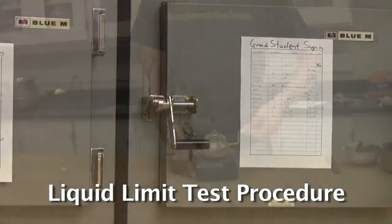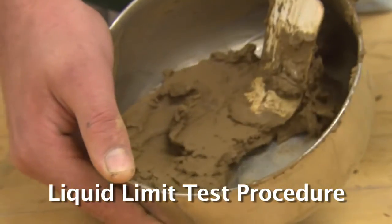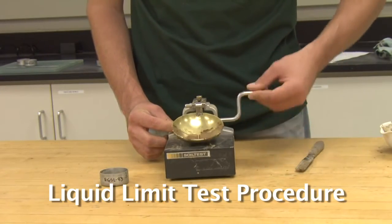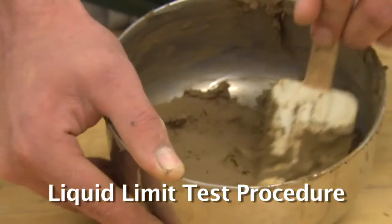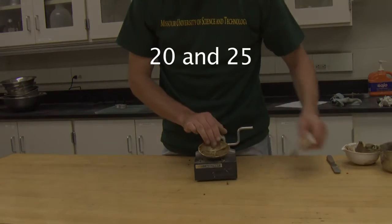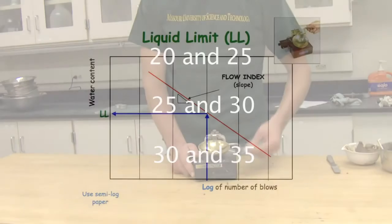If the number of blows falls below 15, mix the soil to dry it out, clean and dry the cup, and repeat the test. If the number of blows falls above 20, add moisture to the soil, mix it, clean and dry the cup, and retest. Repeat the procedure to get tests between 20 and 25, 25 and 30, and 30 and 35 blows.